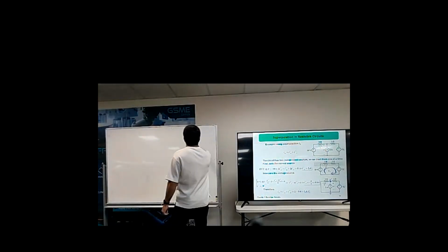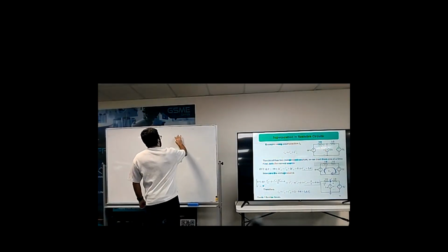Okay. I write one KCL here. I can consider here as E1, but try to use the variables you have on the circuit. That's easy. If here is ground, how much is here? V volts. I can consider this variable as E1 or V. It's only notation, it doesn't matter. So for me, it's easier to consider here V, here 10 volts, here 2ix.